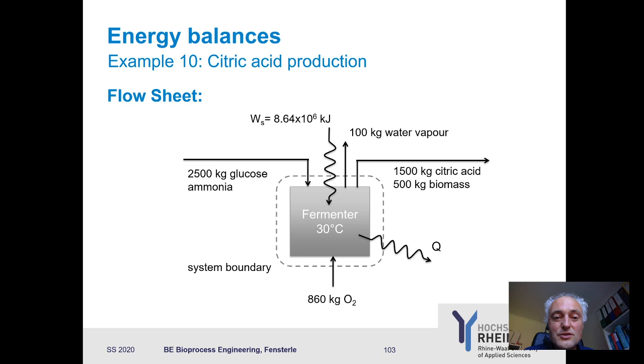And now comes the good news. We have the value for the oxygen consumed here, and it is an aerobic process. So the cool thing is, we don't need to complete the mass balance here because we have the oxygen. And then things get very simple, because at the end we just need to put this oxygen consumption in the equation, and that's it. So let's just solve it, and you will see that in principle it's just 3 lines, and that's it.